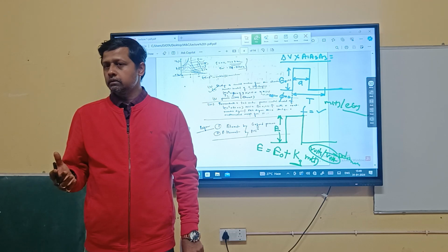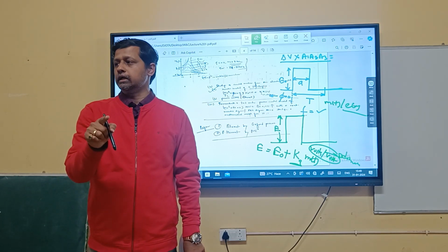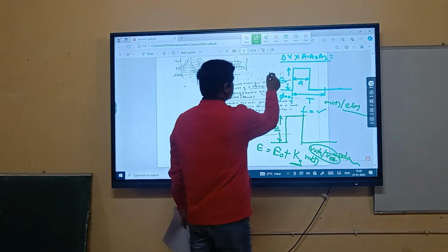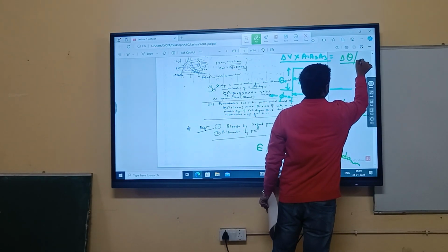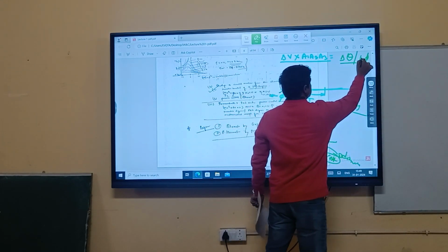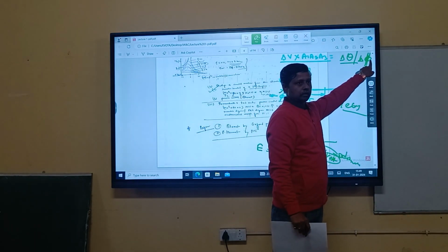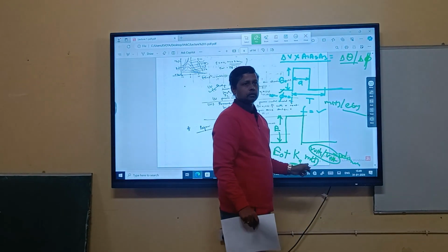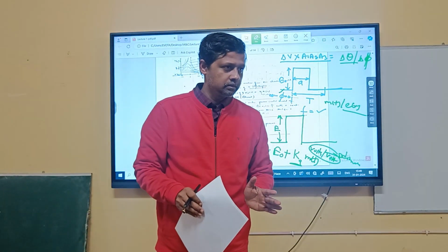Difficult, na? But if I can add one more device in your circuit, a phase shift amplitude detector, where this delta V you ultimately change to delta theta or phi, whatever you write. In this case I have written phi. So changing phi, now my data is changing with respect to phi. Unwanted signal is still changing with respect to amplitude. Can I identify? Easily? No.